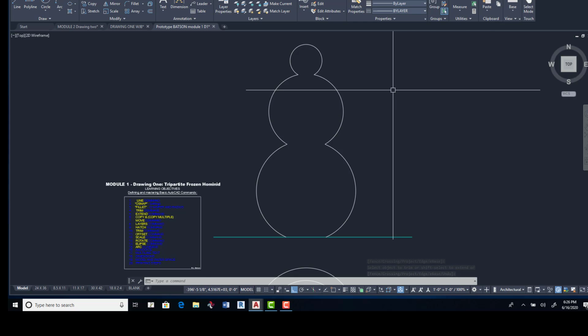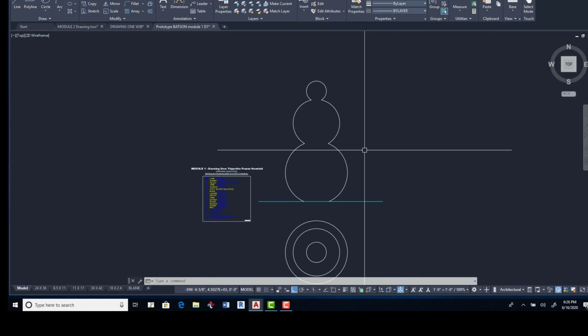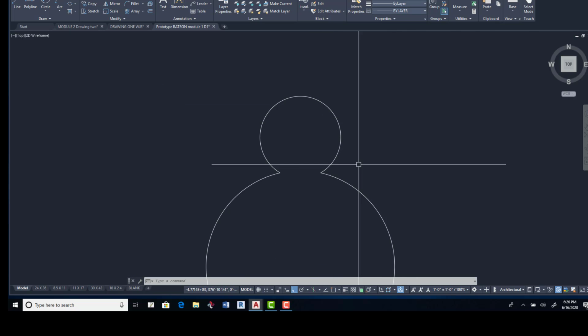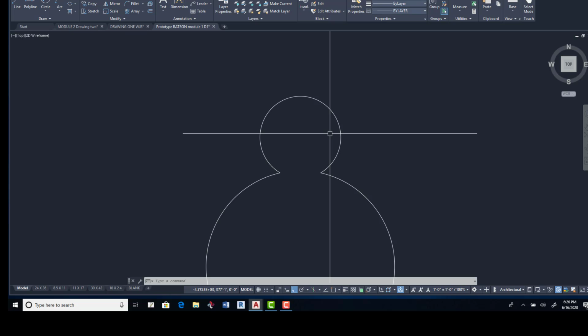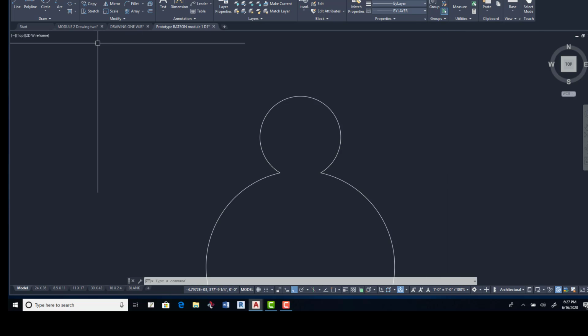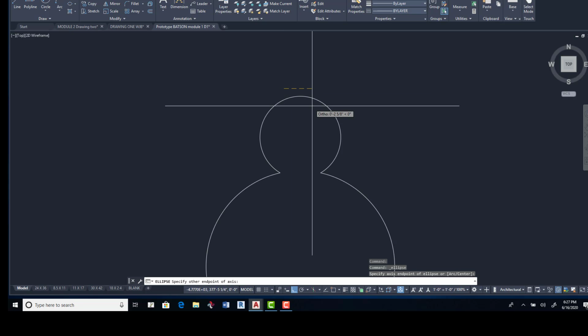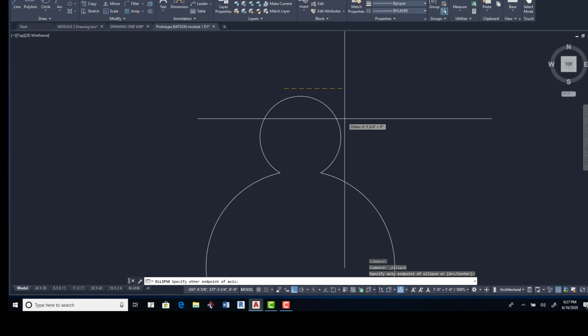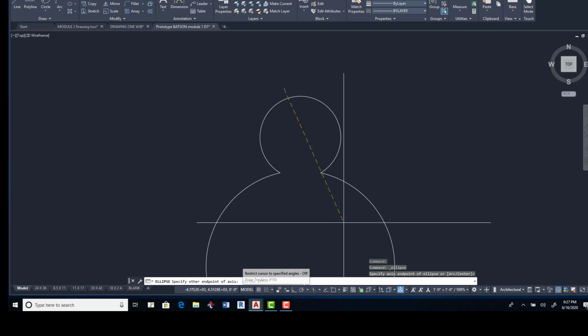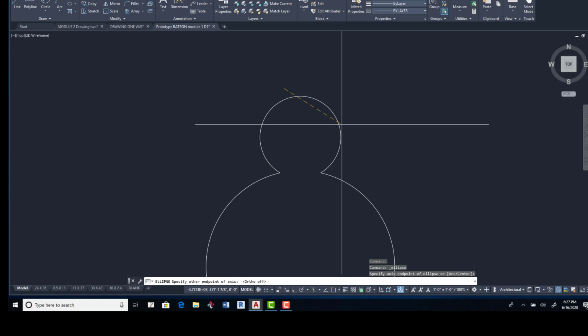So wonderful. So now what we're going to do is we're going to place the hat on the head. And this is going to be done using your ellipse command because it's an ellipse if you look at that. So let's go up here to ellipse. Look at that. Ellipse. And like the circle, click on the cascade area. There's certain ones here. Let's go to axis end. I like that one. So if you eyeball where you think the edge is and you come over here, oops, we're going in ortho. So we have to hit F8 or go down here and uncheck it. So he's got a sort of gangster's tilt here. There you go. Left select.